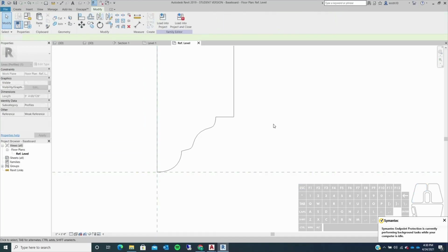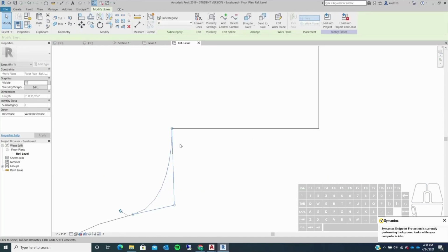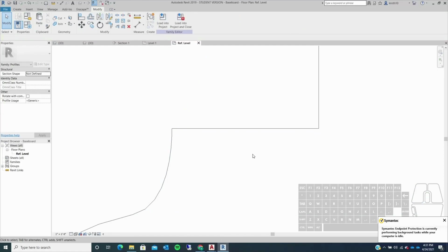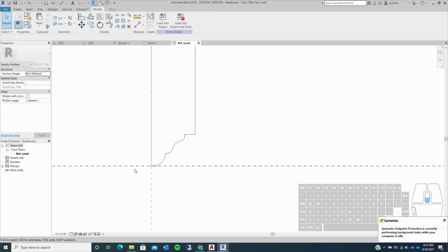Okay, so for this spot, what you need to do is click on this arc here, and then click on this end point where it says drag line end. You want to pull it away, and then you want to hover back over there until you get this pink square snap, and then you want to release it. And then it's going to be snapped correctly to that segment.